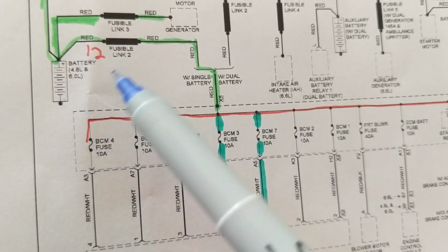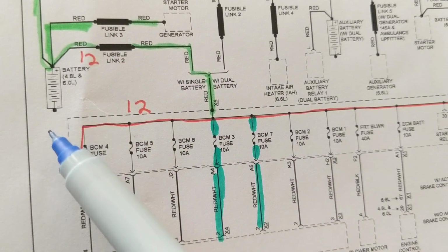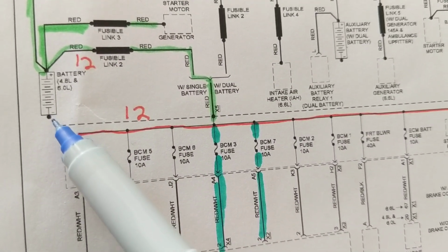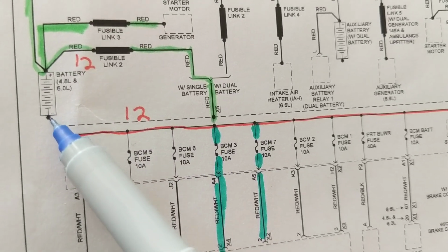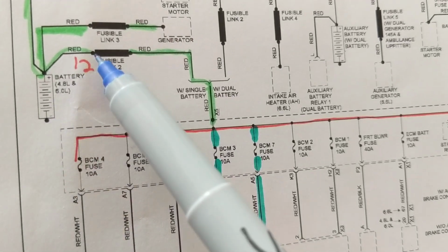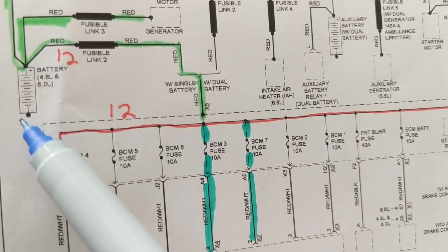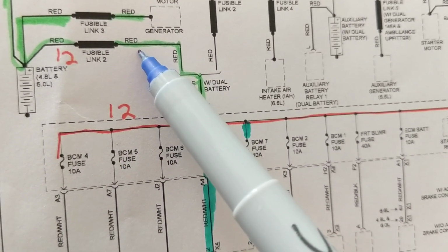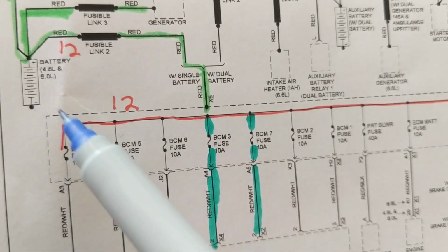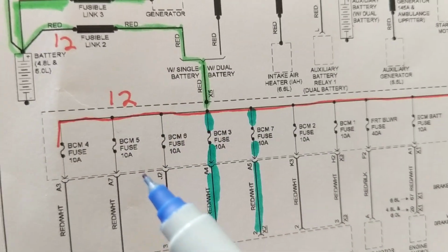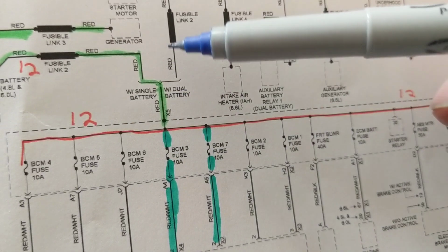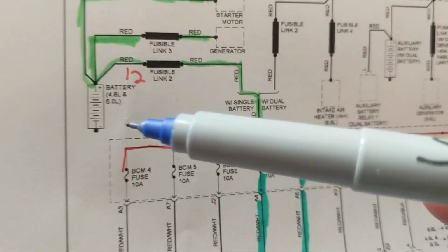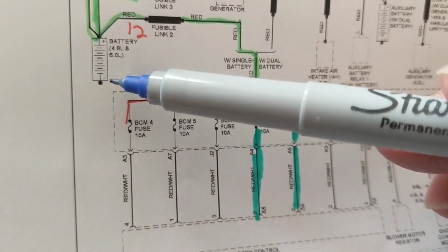We always leave one probe at rest, and with reference to that point, we say with respect to this point, this is 12 volts. With respect to this point is 12 volts. With respect to this point is 12 volts. So we don't need two probes moving at the same time. One is at rest, and that's the black one, the reference to ground.